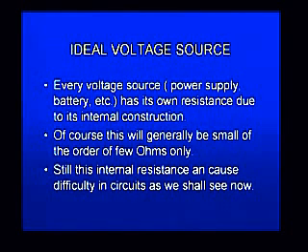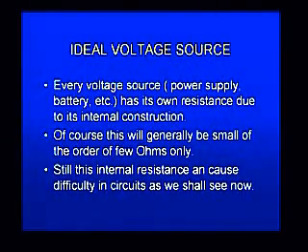The whole of electronics is to be learned by going through very precise concepts which are very useful in the whole application of electronics. The first concept that I would like you to understand is about the ideal voltage source. We make use of voltage sources by way of power supply or battery, but we should always recognize that each one of these devices, the power supply or the battery, will also have a resistance of its own, which is called the internal resistance of the device.